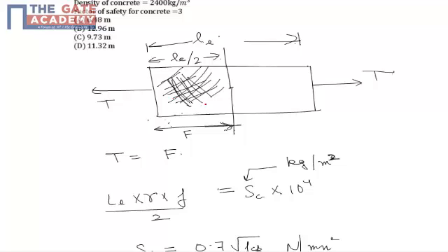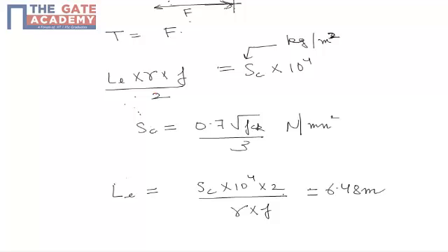That's why this is called a contraction joint, and we know that whenever a material is subjected to contraction, the stresses that are set up are tensile in nature. So I am just equating this tensile force with frictional force. The force on length Le by 2 comes out as weight multiplied by coefficient of friction. It should be equal to the net tensile stresses.